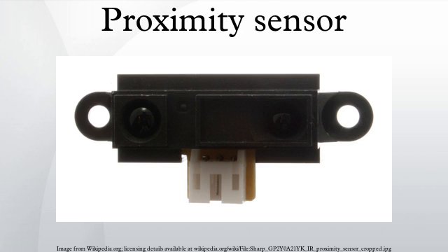The maximum distance that this sensor can detect is defined as the nominal range. Some sensors have adjustments of the nominal range or means to report a graduated detection distance. Proximity sensors can have a high reliability and long functional life because of the absence of mechanical parts and lack of physical contact between sensor and the sensed object.